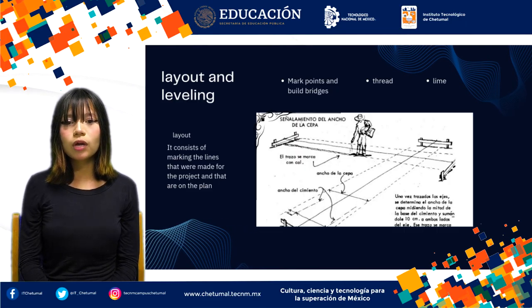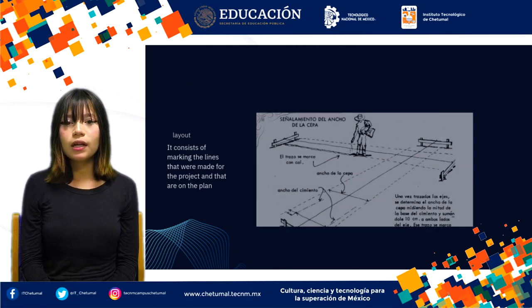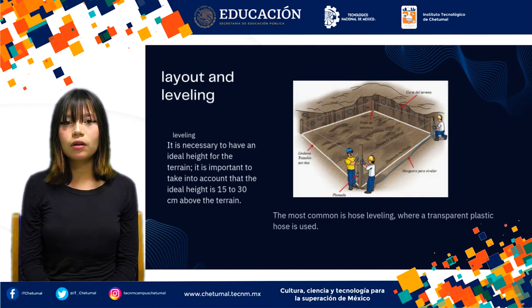Reinforced concrete, the most commonly used in large structures, like columns, beams, and slabs. This concrete is reinforced with steel bars to increase its ability to withstand both compressive and tensile stresses. Ready-mixed concrete. This concrete is prepared in a plant and transported by trucks to the site. Its main advantage is the consistency and quality of the mix, as it follows precise proportions of water, cement, and aggregates.